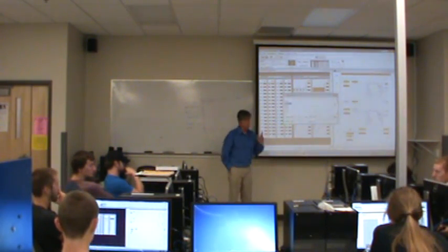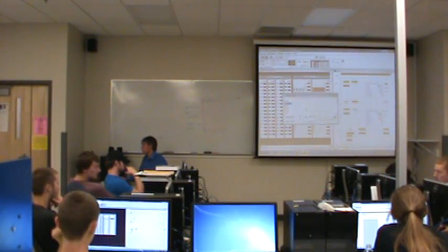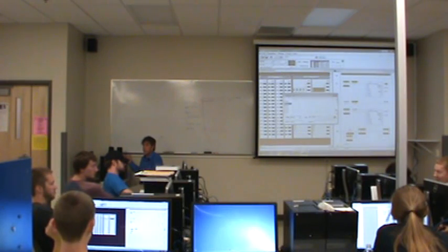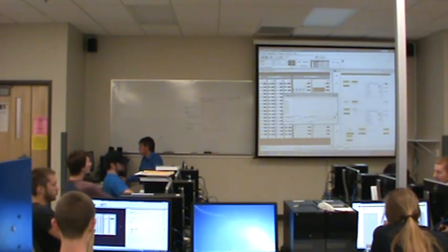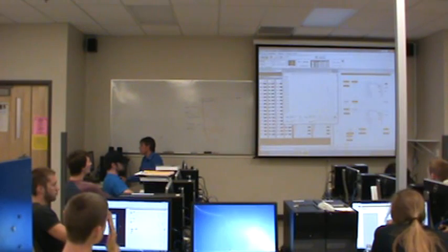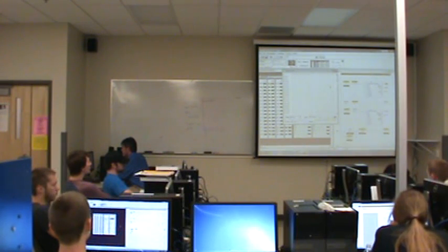Now I'm going to show you one more thing about this program, because you notice I've got all this data in memory, and all this data is arbitrary. I can make it do anything we want. Okay, let me prove that to you. I am going to change the bit patterns in memory. I'm going to basically just flip them around. I'm going to make it count backwards. Okay, so put a 1 here, put a 0 here, 1, 1, 1.